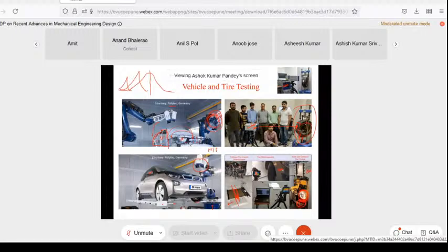Now, as the contact changes, you will have the normal force that is being generated, and based on the normal force you will be able to find what the longitudinal force is. Now you can also keep your tire here and turn it. When you turn, you will get your wheel, which will be something like this. The contact region will be something like this. So you can find out these angles also.